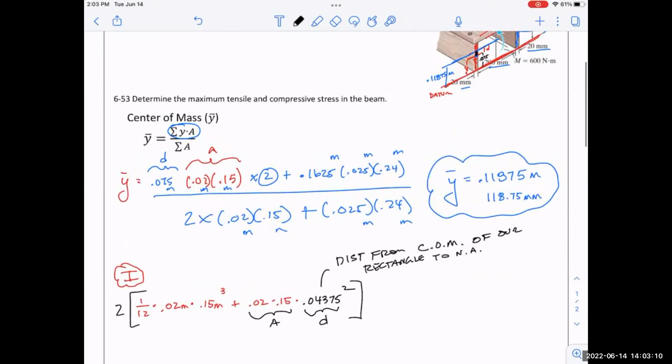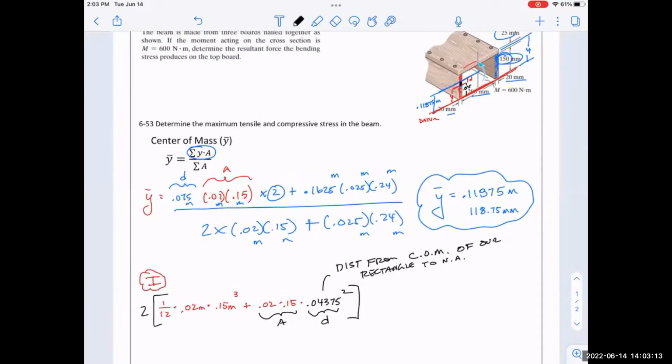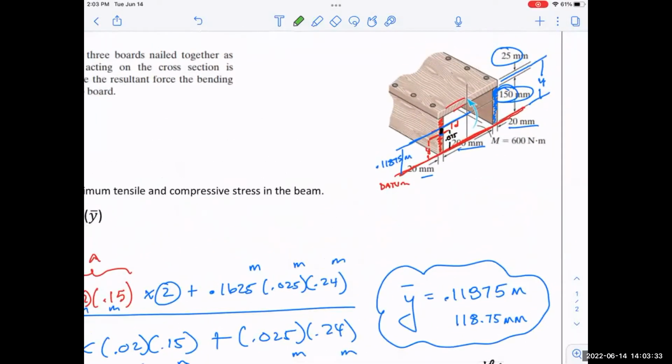And now let's move on to that one up on top. Down to our neutral axis or your center of mass. Yeah, that original shape, that original red datum that I stuck there, if I had stuck it on top, then I would have got a totally different value than you, because then I would have got that distance right there. But had you gone from the top, you would have got a different number, and we'll still get the same answer though. That's what's kind of cool.